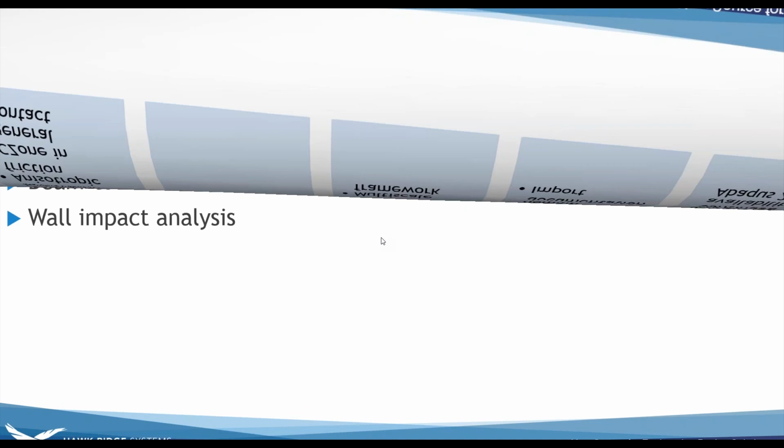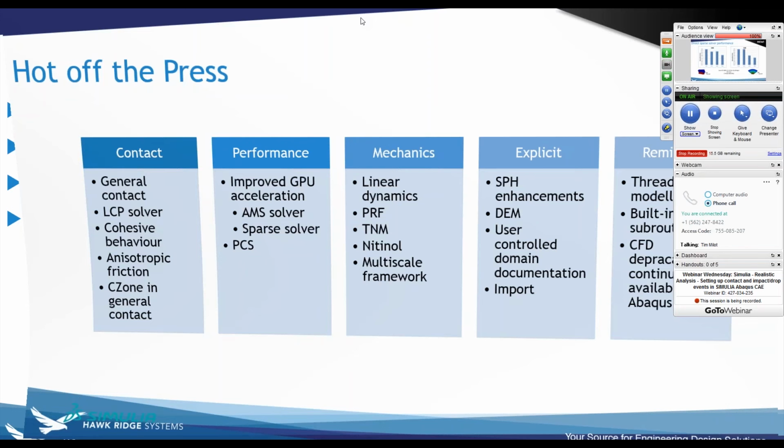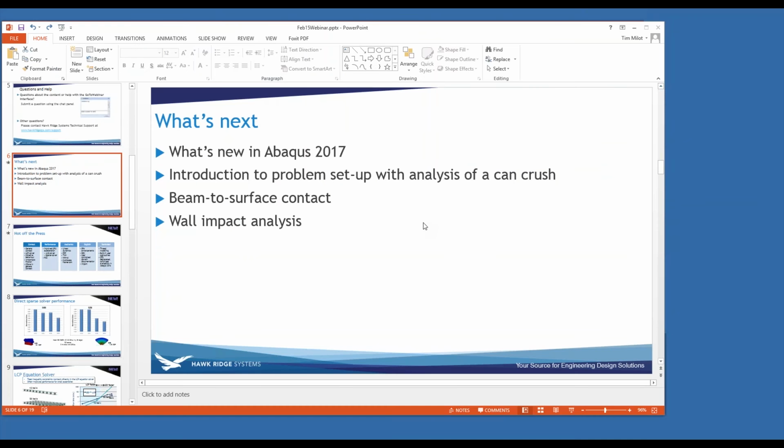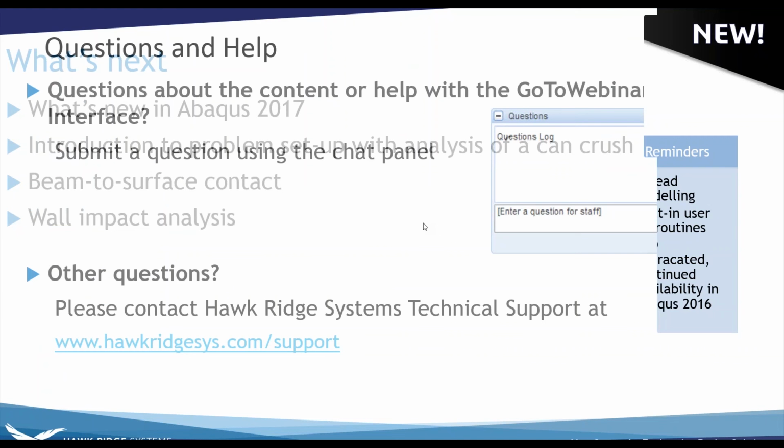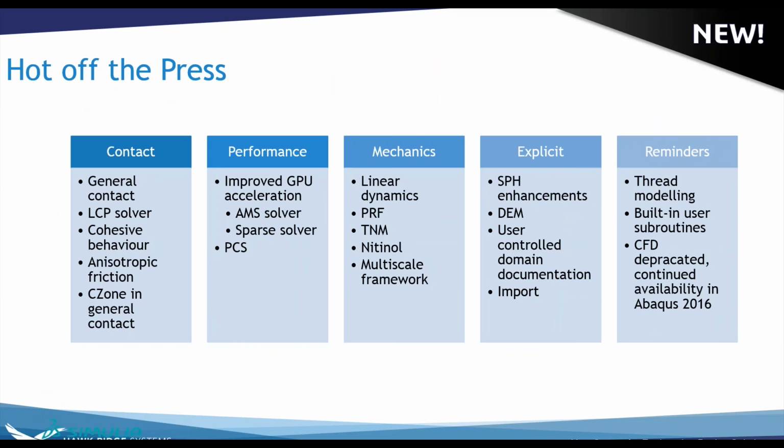The mile-high summary is that we've had a lot of enhancement to the contact and constraint controls. There's been some research put into the extended finite element fracture mechanics models in Abaqus Standard, and they've introduced a new feature called a linear complementarity problem equation solver in Abaqus Standard, which basically linearizes contacts within small displacements, like you may see in a ball bearing, to reduce your computational cost.